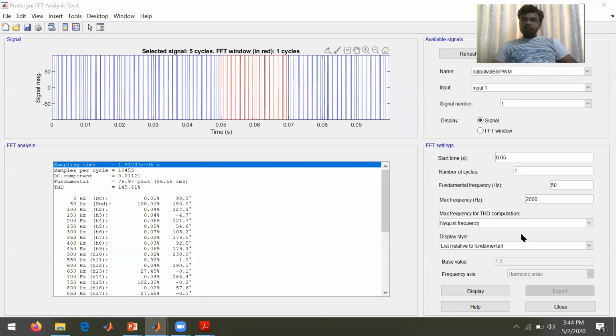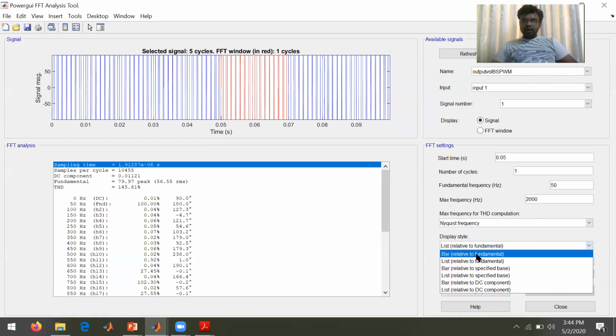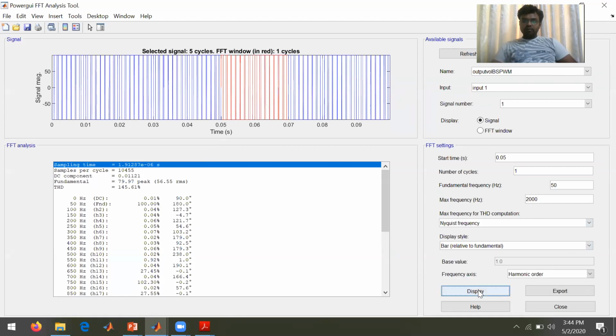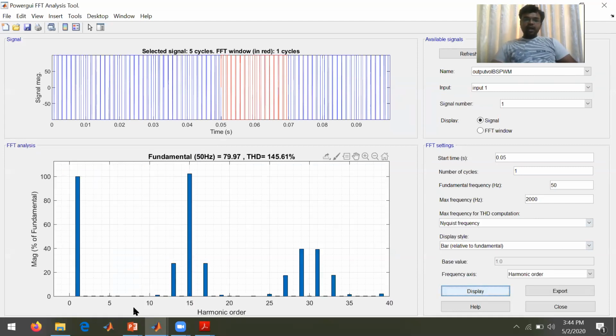Okay, right. Now first band and the second band I have to show, right? So what are this first band and second band? If you go for the bar, you will get some. So this is the first band of harmonics. First band means where you are getting the first band at MF is 15. Second band, what happens? 2 MF plus or minus 1. That means 2 into 15, that means 30 plus or minus 1. That is 31 or 29.